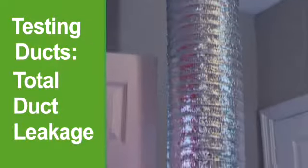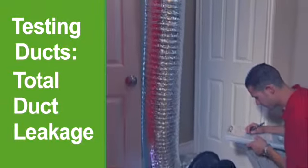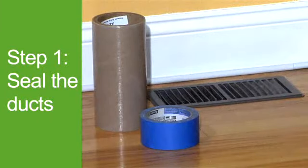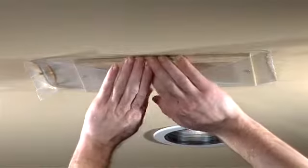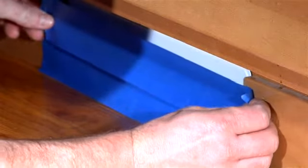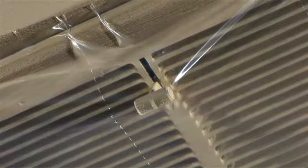We'll be performing a total duct leakage test after construction, but the same principles would apply if you were doing it after rough-in. In order to generate a readable pressure difference within the duct system, you'll need to isolate the ducts from the house. To do this, go around and seal all of the return grills and supply registers, as well as the furnace filter slot. Be sure to seal completely around the diffuser handle.